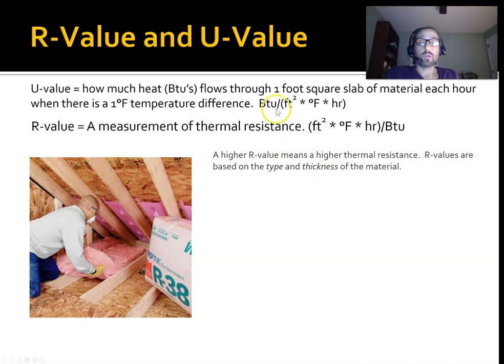Whereas with the U, because that's transmittance, you want a really small U. So it's hard to wrap your mind around small U meaning really good. If you tell a homeowner, look, you have R10 in your attic, you need to add R30, and that's going to give you R40, it's really easy to understand that R40 is 4 times R10. Really easy to remember. So that's really why we use R.